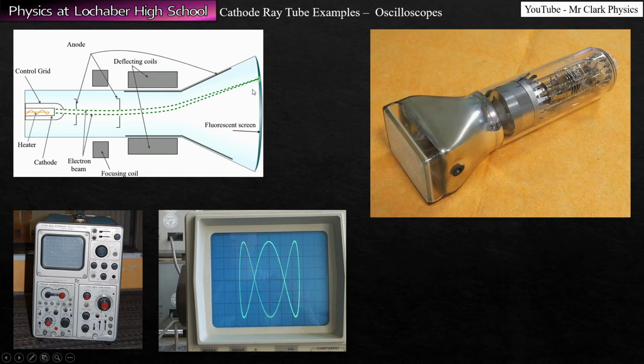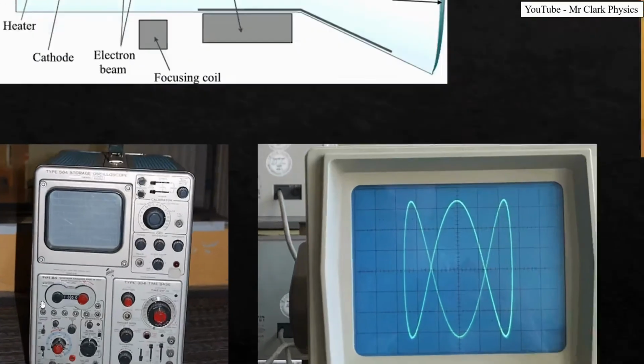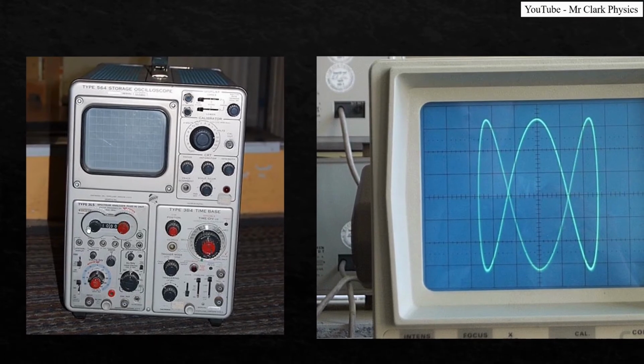A common thing people aren't aware of, for example, is if you use a voltmeter to measure an AC voltage, it typically only works if the frequency of that signal is pretty close to the mains voltage frequency. If you try and plug it into other things, it just doesn't work at all. The electronics and the software involved has certain assumptions built into it, and that's a problem. You can get apps that function as oscilloscopes, and they are nice and flashy and all the rest of it, but there's always that problem.